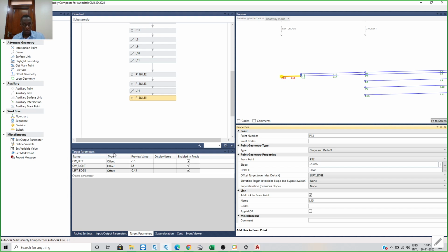So for the first scenario, we are going to use the normal, which is the normal requirement by the design requirement. So I don't know if we have seen our side slopes from our Uganda manuals for the pavement layers. Let us say that we are going to take on the 1 to 2 as our side slope.